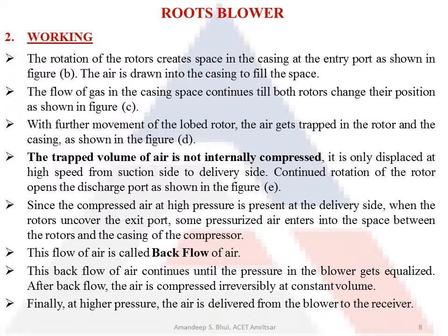The trapped volume of air is not internally compressed. It is only displaced at high speed from the suction side to the delivery side. Continued rotation of the rotor opens the discharge side of the rotor.